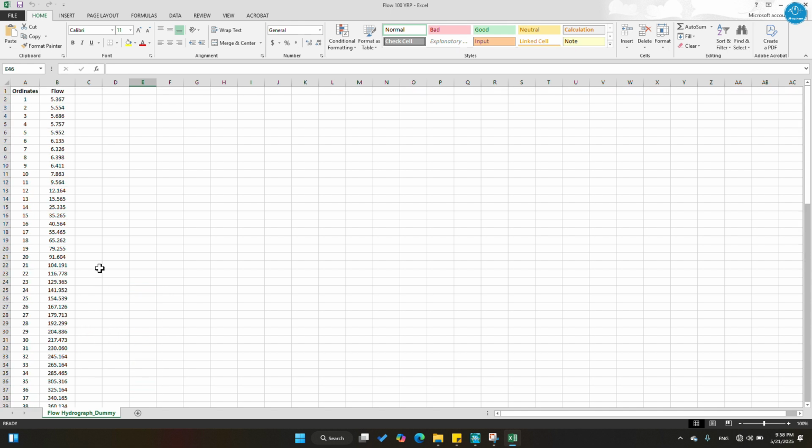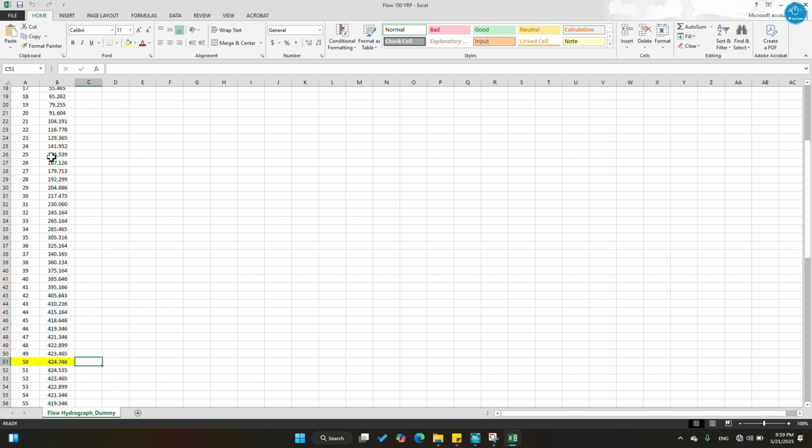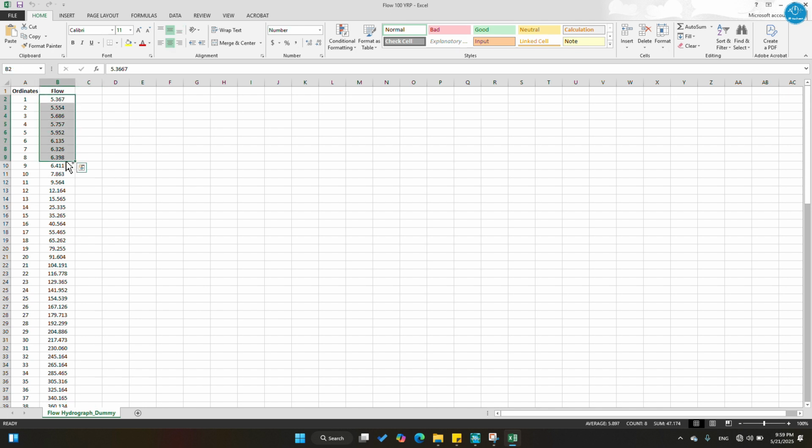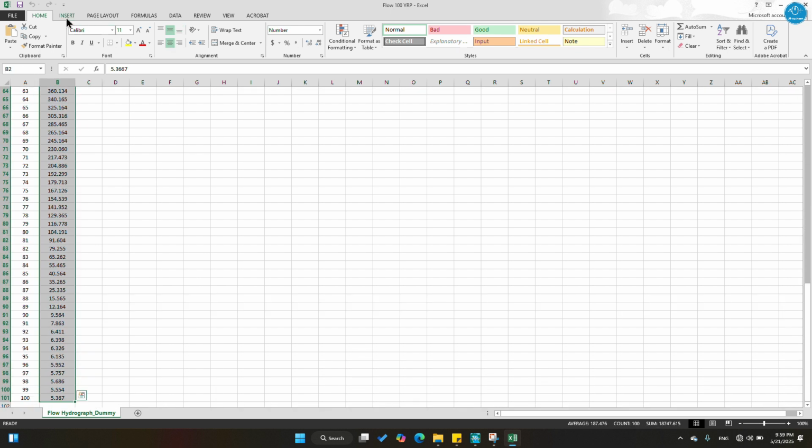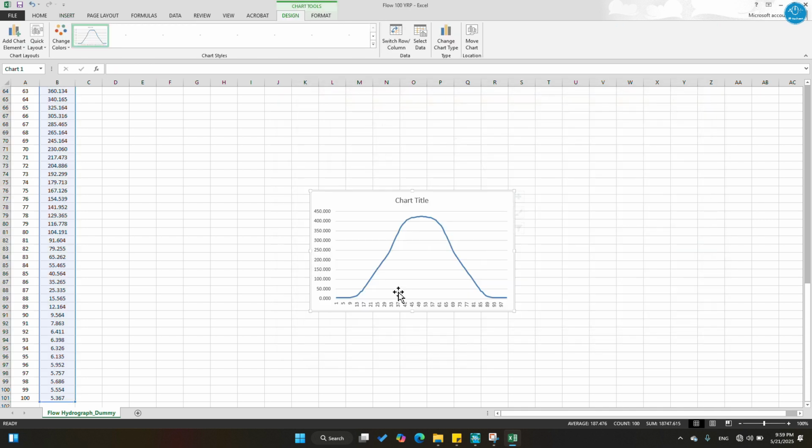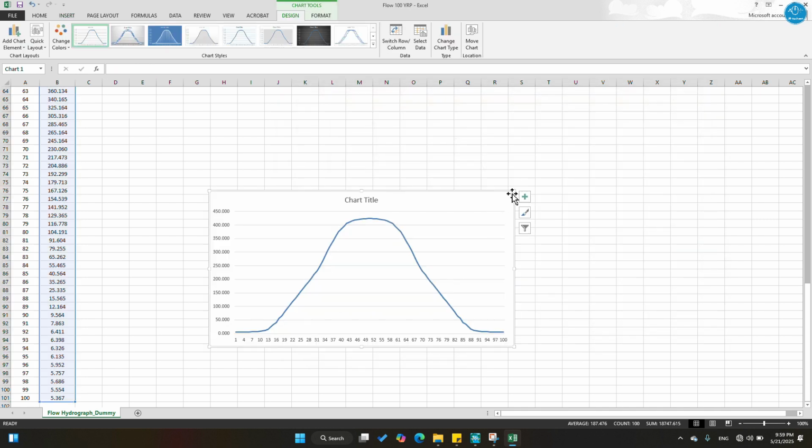It was of a 100-year return period, with a peak flow of 424.746 cubic meters per second, and using mathematical modeling I created this flow hydrograph. We have different types of options, tools, mathematical techniques or equations which can create the flood scenario flow hydrograph using the peak discharge. I used the unit hydrograph method to simulate the flow hydrograph of this river. Let's see the graph. Here it is like this.